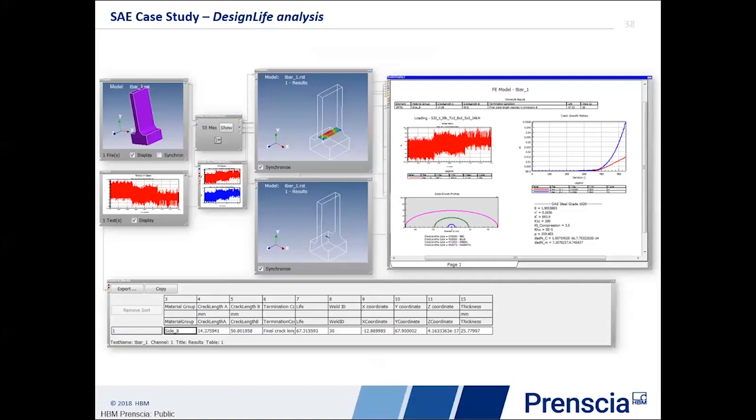And again, what we started with was our T specimen, and we actually had weld locations on both sides of the model. Some of these loadings are either fully reversed or are loading in both directions. So which side of the model starts cracking first is in question. And so that initial calculation is done just with standard seam weld, looking at the stress histories on the model.